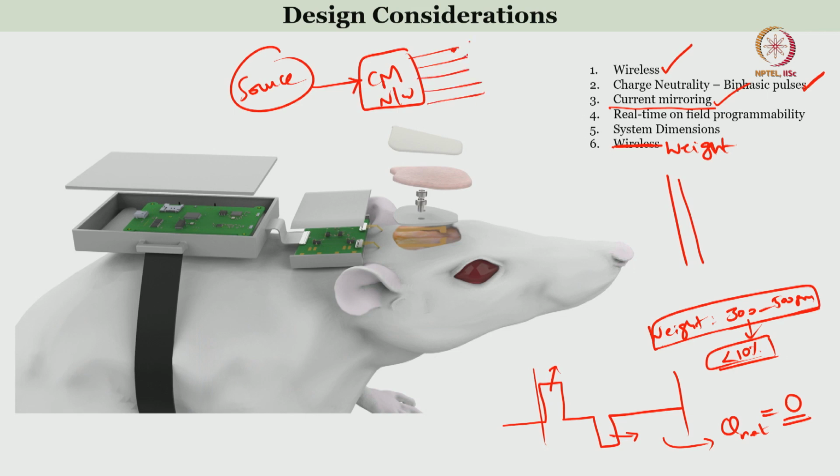So you have output 1, output 2, output 3, output 4, output 5, so many outputs that you can have. If you make the source stable, then your output currents may not be stable. Of course, a little bit of design consideration on the current mirror will come into the picture. If that is taken care of, then multiple copies of the current are possible using the current mirroring technique.